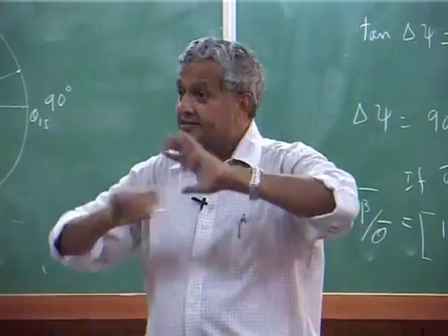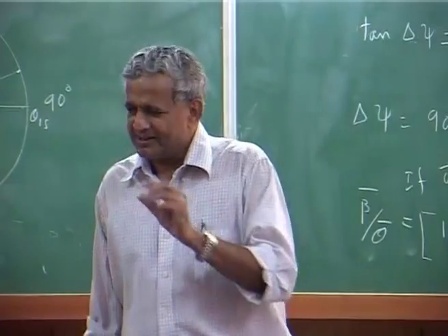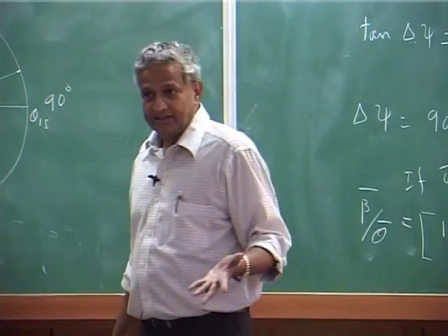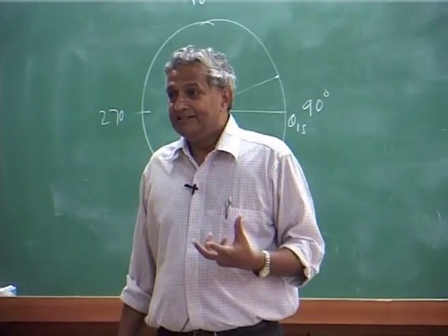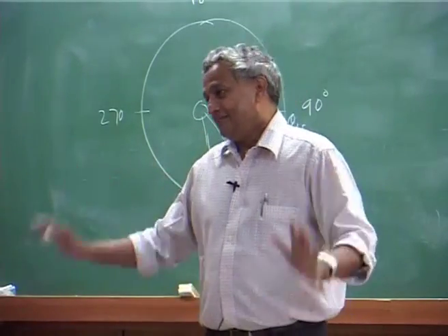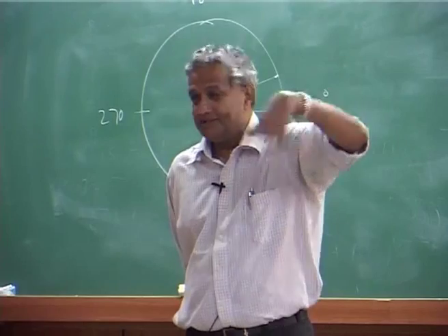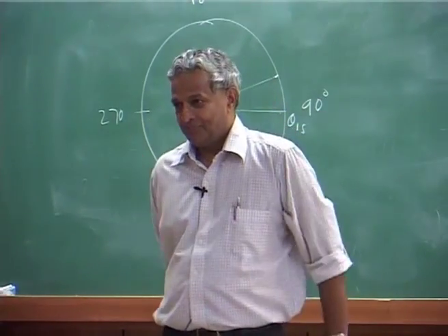You have to analyze the full helicopter. Industry, for ease of understanding, can do a little bit of decoupling, but otherwise it is not possible to decouple the longitudinal and lateral degrees of freedom. So, you have to solve the full 6 degrees of freedom, all coupled, in the flight dynamics.